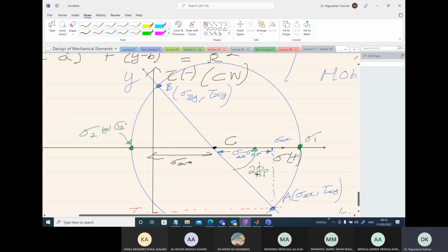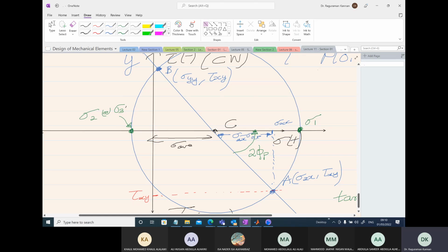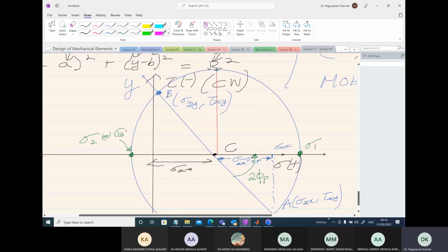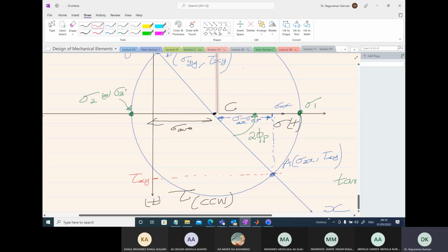Okay. Now in the Mohr circle, let's also figure out the maximum shear stress direction. Draw a straight line passing through the center vertically. And wherever it intersects the circle, that will be your maximum shear stress. So let's assume this is the center here. It may not be exactly the center in the figure, but assume that it is.